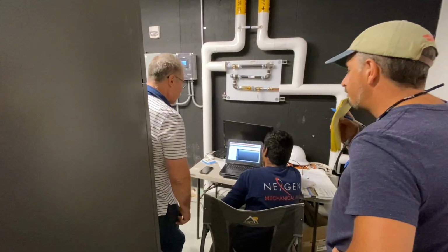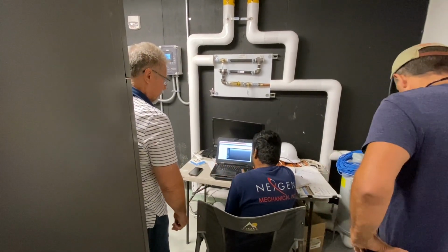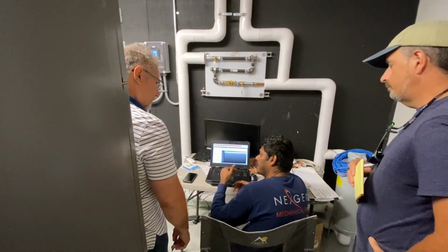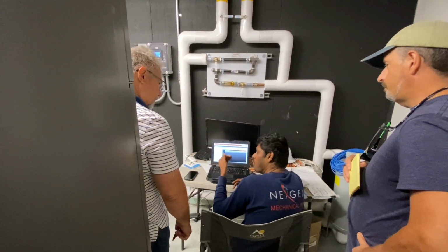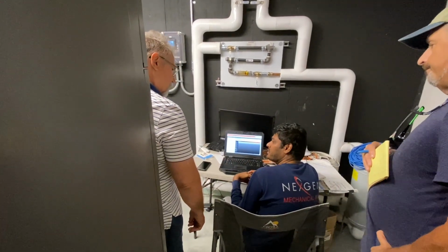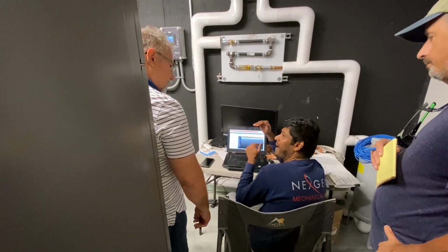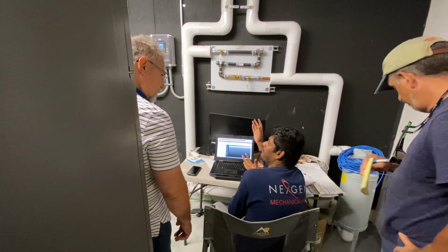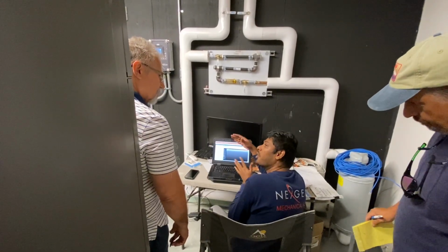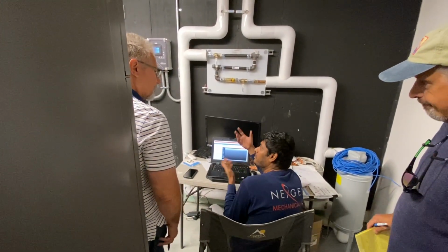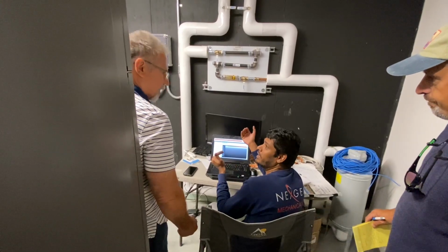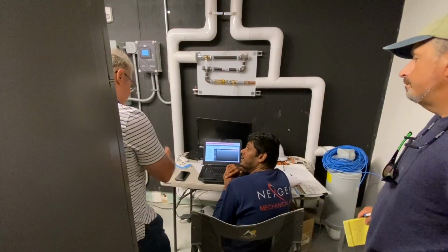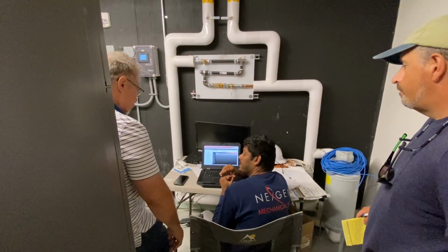Okay. So I recommend having at least 1 degree above for cooling, at least 1 degree above the occupied set point, and for heating 1 degree below the occupied heating set point. But people see they do match all the time. Then there is no standby concept. Irrespective of the occupancy status, it is always in occupied set points. In that way, we don't conserve any kind of energy. I understand. I like the two degrees, like you were saying. 74, 76, whatever. 66, 68, or whatever. Exactly, 2 degrees.